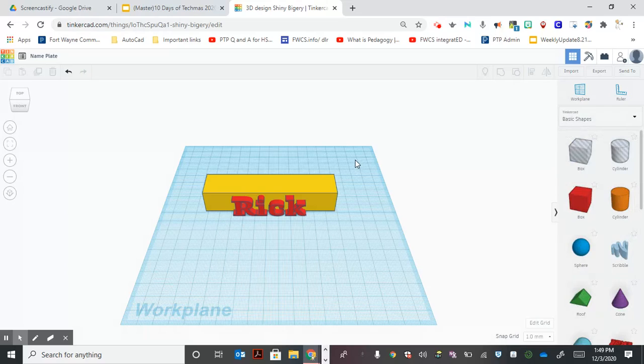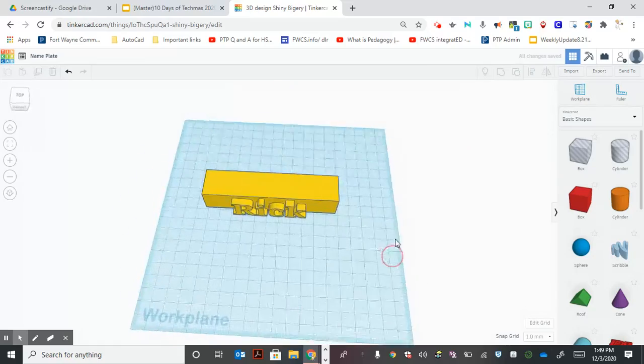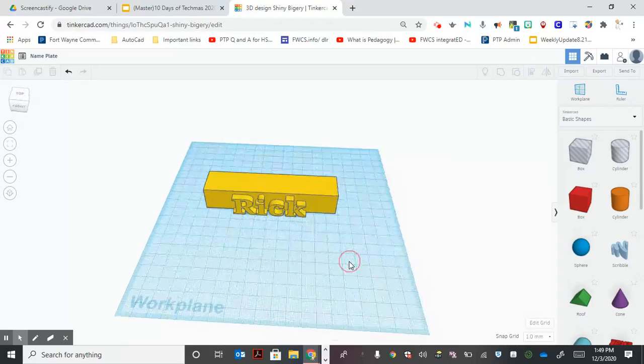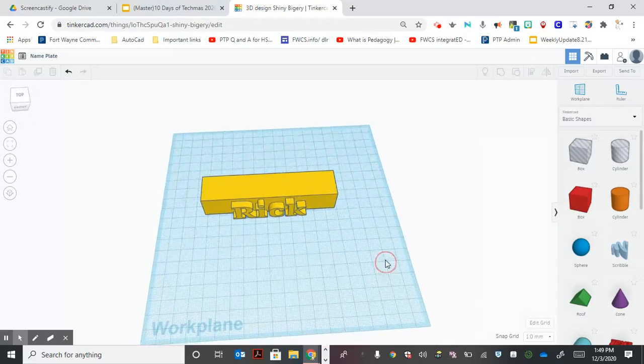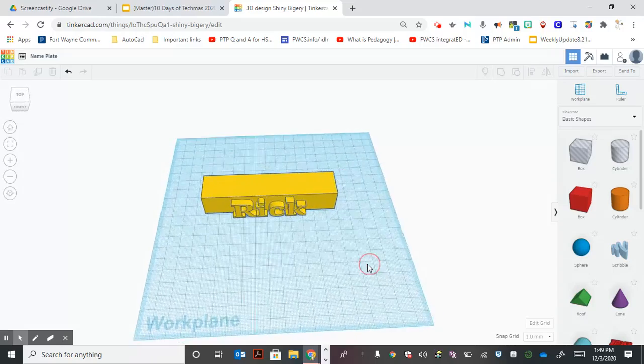So that's how you would generally create a nameplate and put the two together. Last thing I want to show you is, in order to keep them together, if I left click and select over the whole area here, I can come up to this little icon, and it's a grouping icon. When I select it, now it's all the same. Now when I rotate it, that's all considered one model. It's not separate anymore. I would have to ungroup it in order to get it that way.